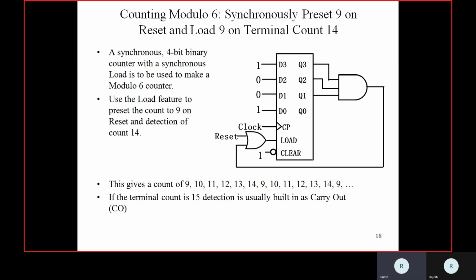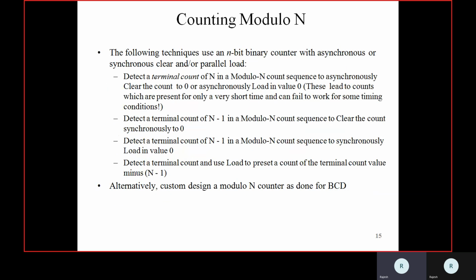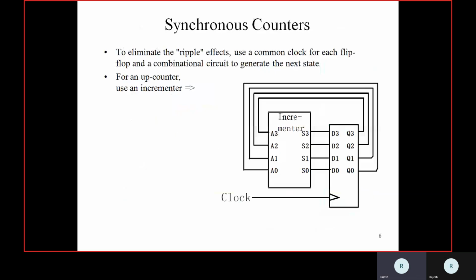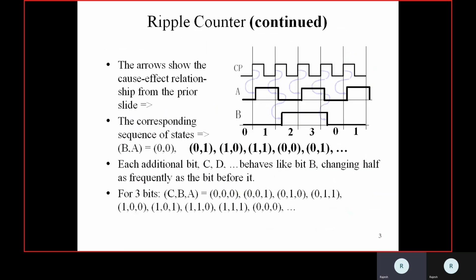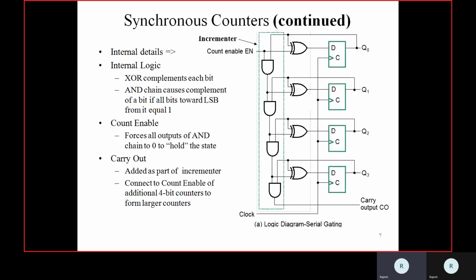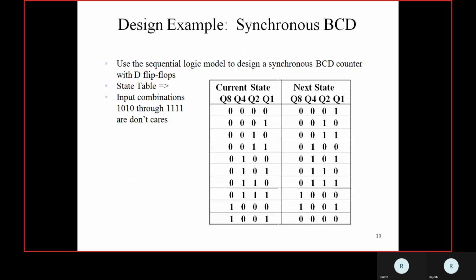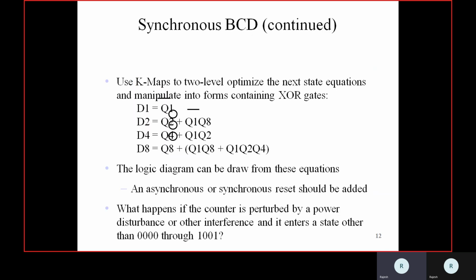So in the exam, you don't need to add all this reset and clear pin. You can just go on designing an asynchronous counter as a ripple counter like this, 2-bit, 3-bit or 4-bit, or you can go for designing a synchronous counter based upon your state table, where taking the current state and the next state, you can generate the corresponding input bits, and for those input bit values, when they become 1, you can generate a K-map, and you can generate the hardware like this.